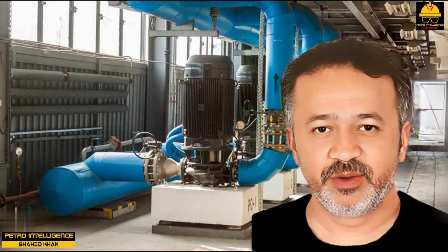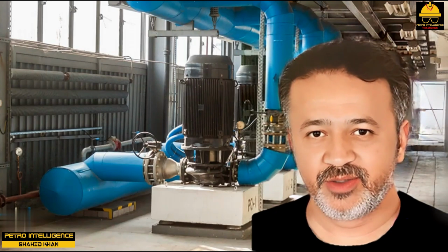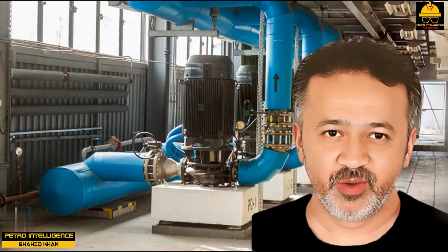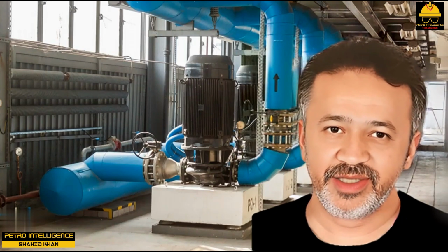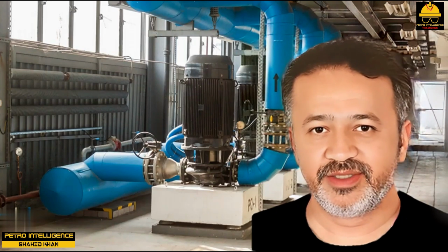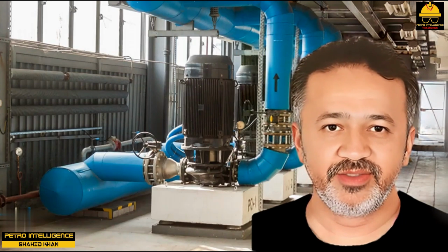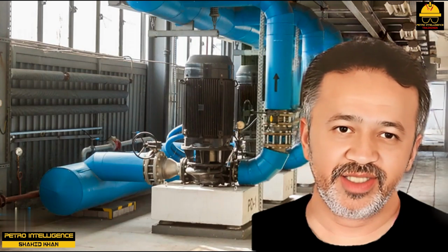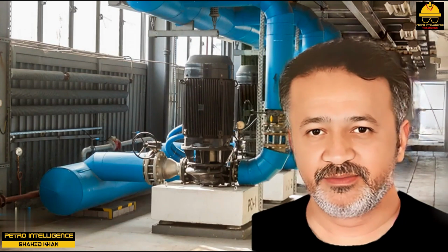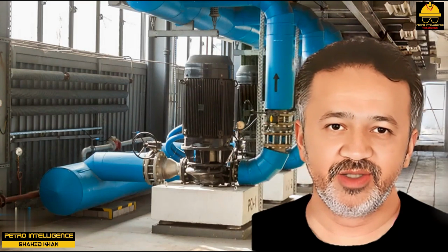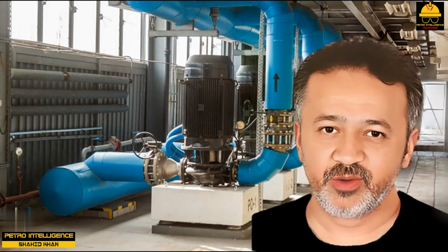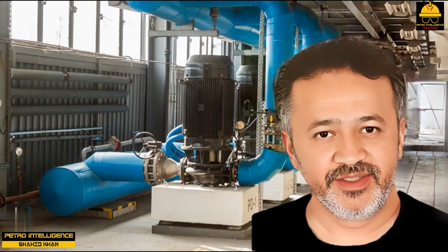Sometimes, the pressure drop across a control valve is so huge, greater than or equal to 100 psi, that it makes a roaring sound. The energy represented by this wasteful delta P is coming from the electricity supplied to the pump's motor. Hence, trimming the impeller also reduces wear because of erosion in downstream control valves.